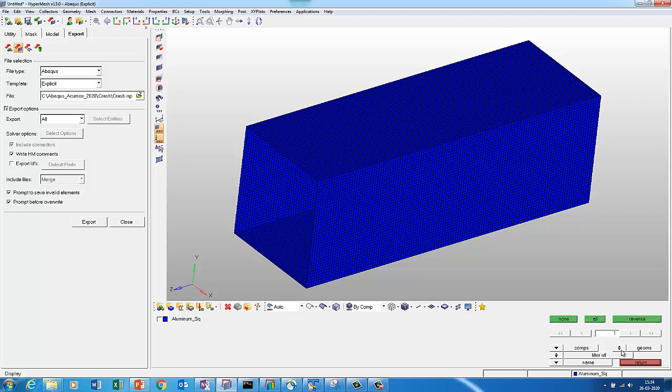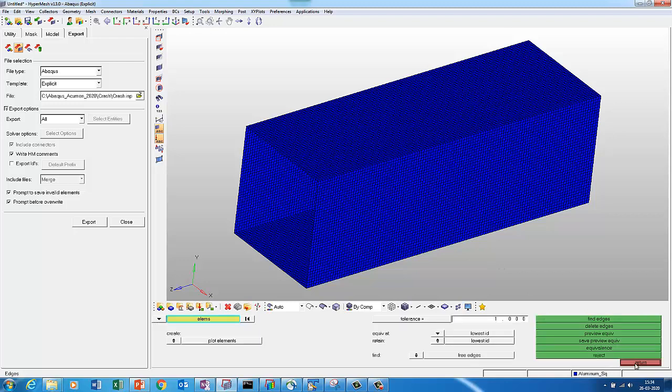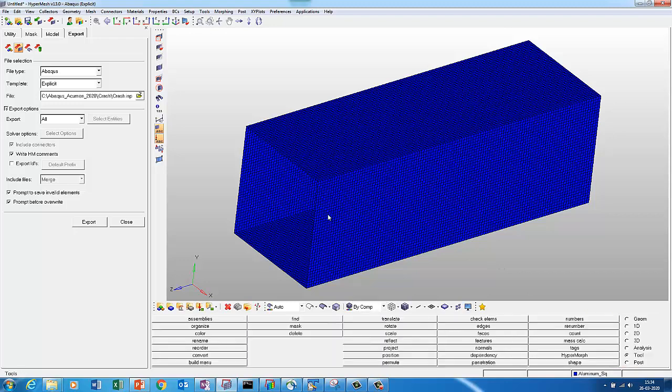So there is element and geometry panel. If you put geometry, it will create all these lines. If you don't want lines, then just remove that geometry and element is on. Now we see the element there. Now this is only an element, it is not defined any thickness or material data, so it is just an element.